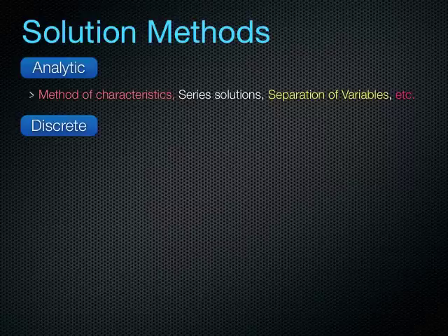And of course, the accuracy of our approximations can hopefully be controlled by controlling the size of our finite elements. That will be mesh refinement, or increasing the order of the interpolating functions within each finite element of our field variable, and that will be the polynomial refinement. And those kinds of things will be offered to you in courses later on, in a finite element analysis course or a finite volumes course on fluid mechanics.